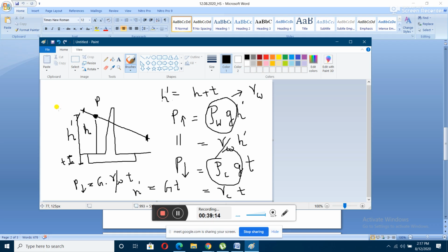But generally what is being done is we provide a uniform thickness considering the head at the extreme point, the maximum head, denoted by capital H. We construct it accordingly, taking that h value as capital H, which is the maximum head, for the determination of the value of t. We can do that, okay. So accordingly it will have a uniform thickness, the t value will be uniform throughout.